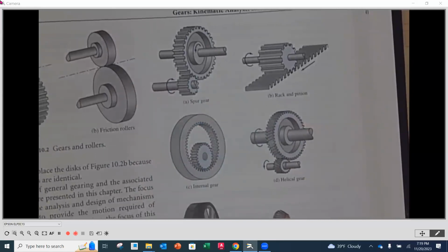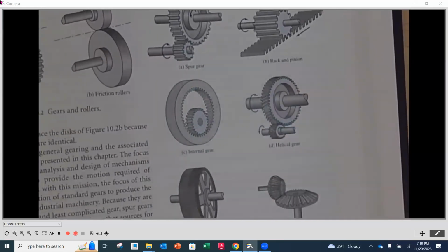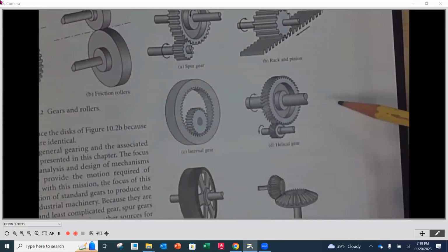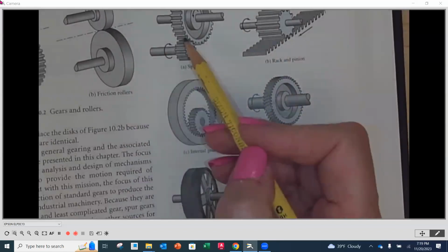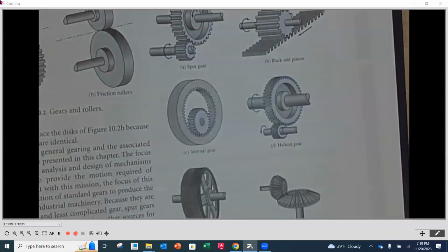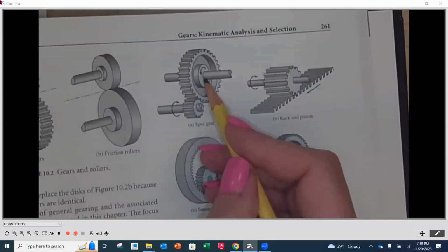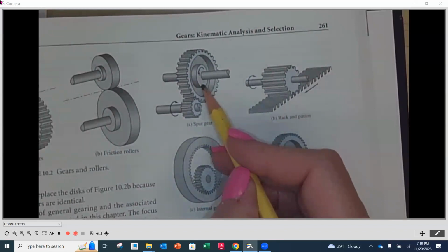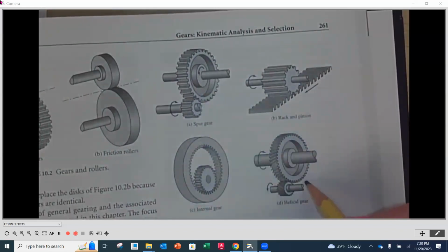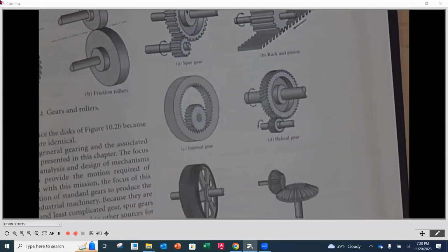So helical gears can push more torque. The other thing that they do, actually two more things that they do, is because the teeth are at an angle, they can actually take what we call a side load. Spur gears can't. So if there's any side load on whatever we're engaging with or what's supported on the same shaft, we wouldn't be able to accommodate that with a spur gear. You have to go with a helical gear instead because it's got the capability to resist side loads.